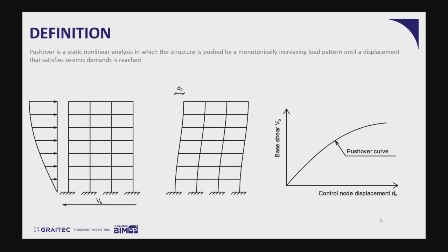Pushover is a static nonlinear analysis in which the structure is pushed by a monotonically increasing load pattern until a displacement that satisfies the seismic demands of the structure. So, in other words, what do we do here? We have a structure. On this structure, we adopt a load pattern that represents the seismic forces applied on the structure. So, step by step, we increase this load pattern. Of course, the proportions of the loads are always respected in the load pattern, so we always respect this shape of forces adopted from the beginning.